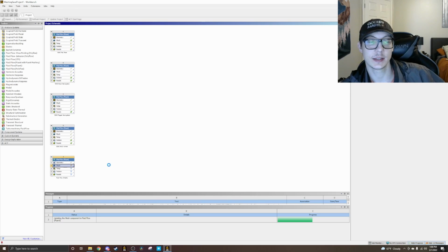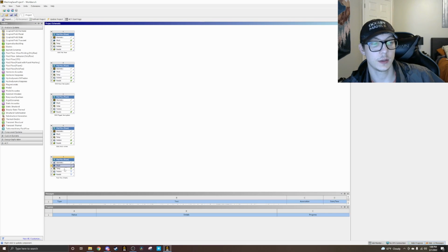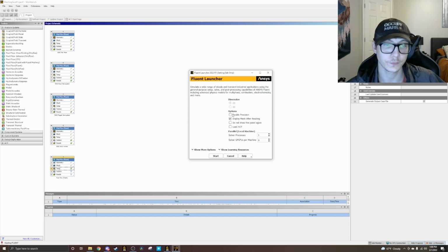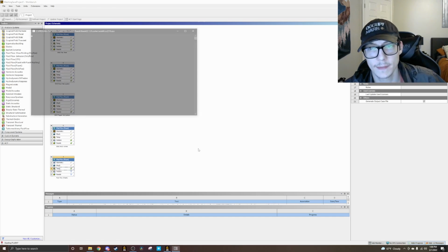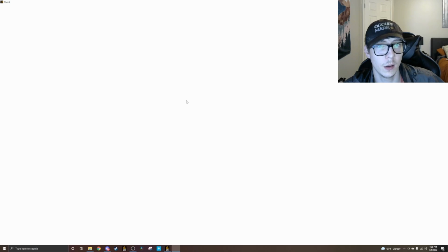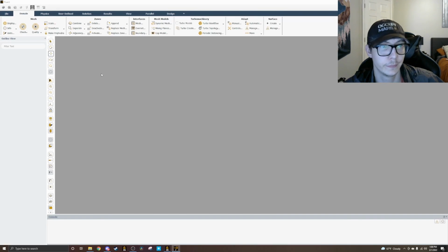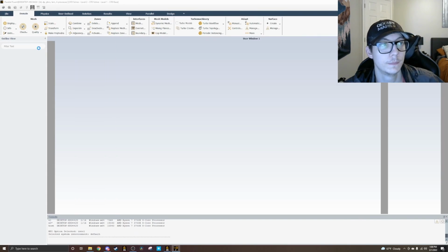And again, this can take a second, but just got to be patient with Ansys. Cool. Mesh is updated. Awesome. So now we're going to go ahead and edit our setup. We're going to do double precision. Crank it up to 4 solver processes, because that has to do with the number of cores you have. I'm on an 8-core processor, so 4 is just fine.